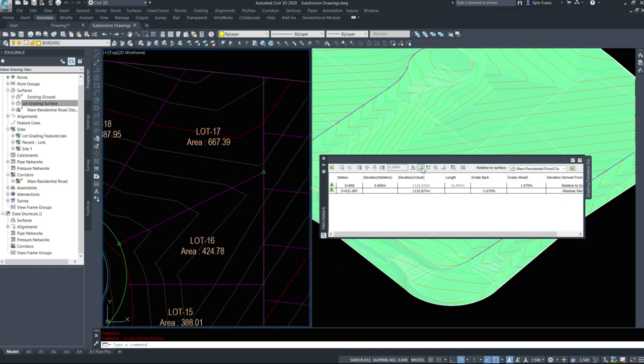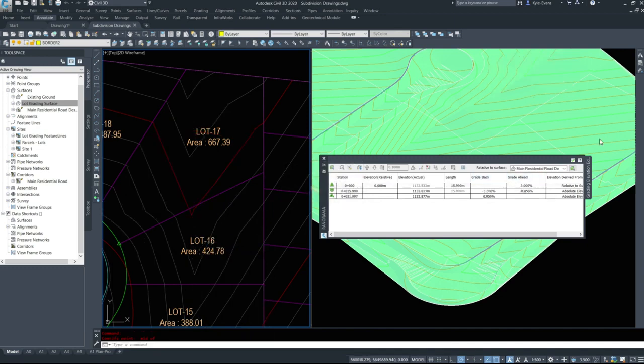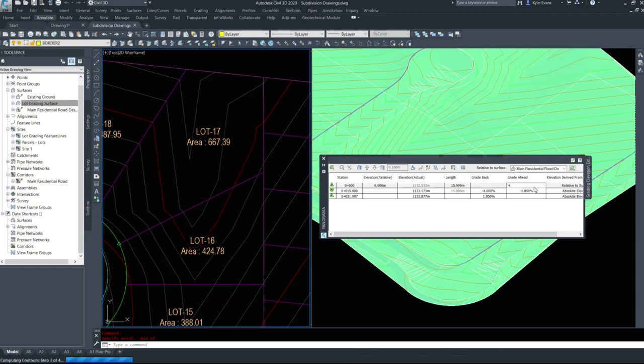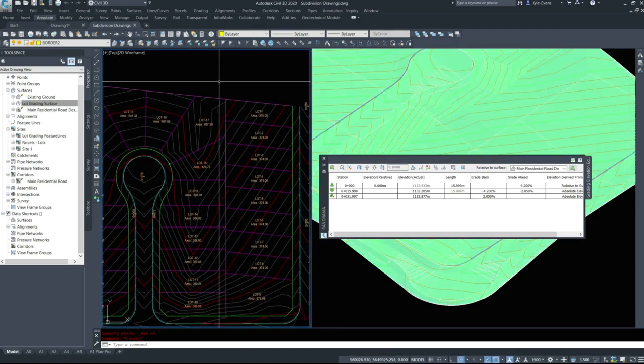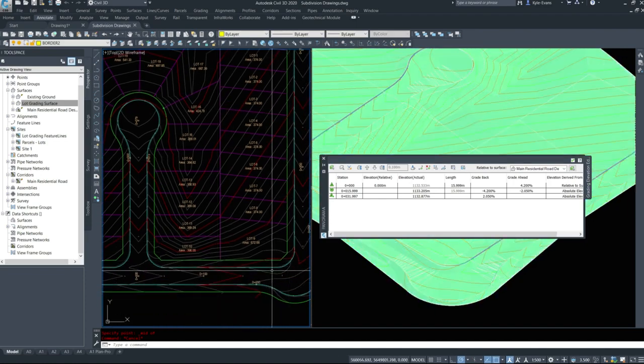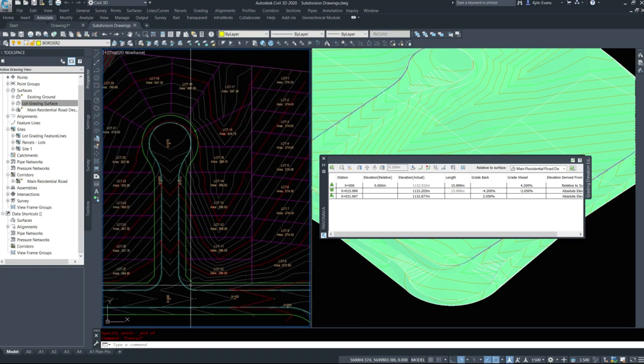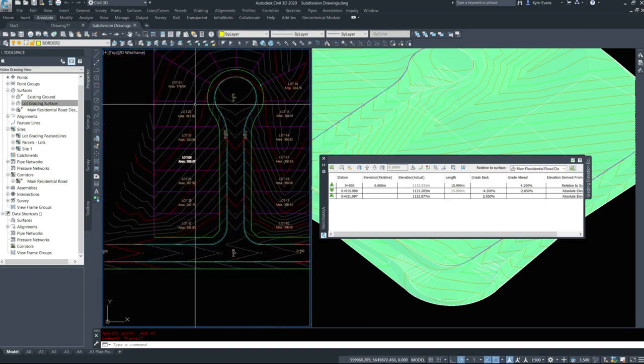that is 1% up, so we will do midpoint again, and we'll go 3% up. And okay, what about 4% up? 4.2. So we're 4.2 up and now -2 down. So there will have to be a back swale behind these lots, which is just a concrete trough for water, because half the lots are flowing out there and the swale will drain to the road and probably down to our low point here. The rest of the lots I've just graded up at 2%.